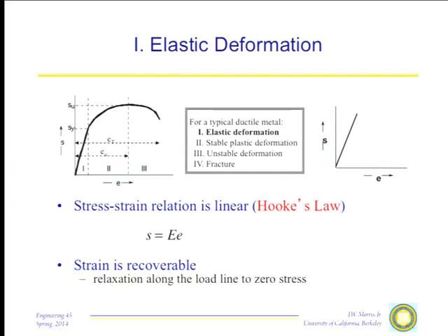However, when materials are processed, it will very often happen that the processing leads to what we call texture. That is, the grains are no longer randomly oriented. They tend to be preferentially aligned in certain crystallographic directions. And when that is the case, you can no longer assume complete isotropy, and you have to take account of the texture in predicting the properties of the material. Doing that is beyond the scope of this course, but let me just warn you that it's there. We're going to assume that materials are isotropic.